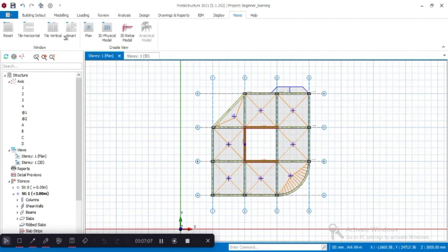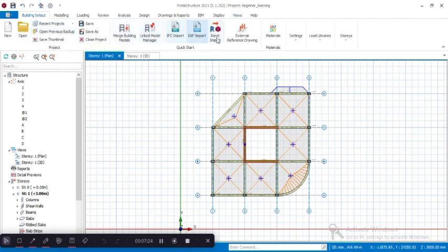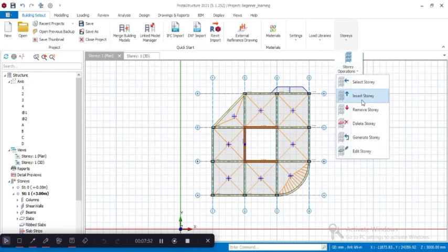Inserting stories and defining building parameters. The final model will be a 4-story building. So we will now insert the other floors. Inside this video, we go to floors, we go to our building setup, then story drop down. This is stories. This drop down. Then insert stories.